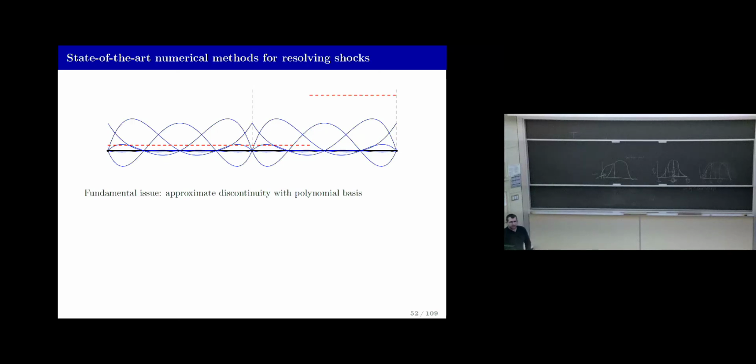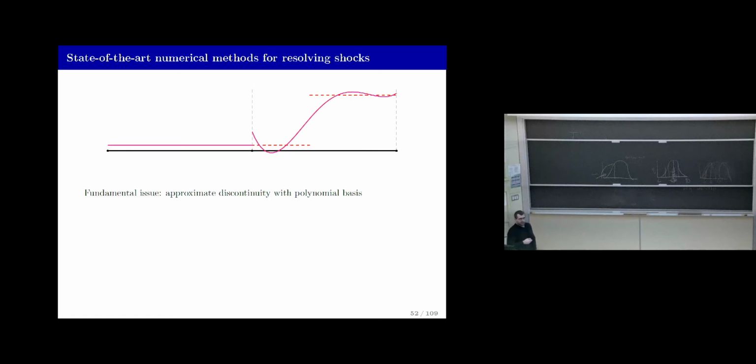Now let's use this basis to approximate it. Everything went beautifully in this element. It was smooth and constant, and everything was nice. Now in this element, everything went bad. You get these overshoots and undershoots that are well-known Gibbs phenomena. I'm not claiming I found a new problem or anything. This is a well-known problem. Now let's say that this variable right here is the density of your flow. It just dropped below 0. So now your code crashed.